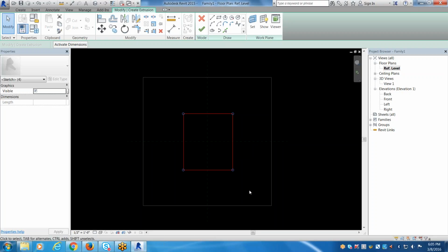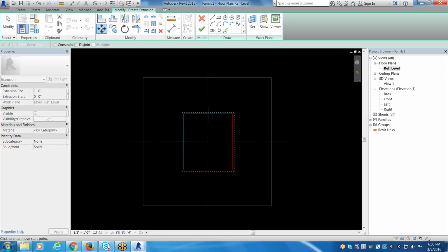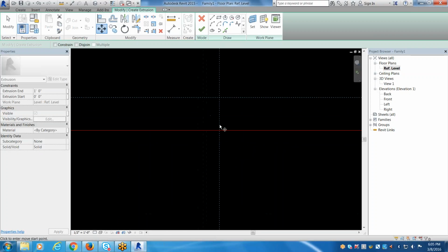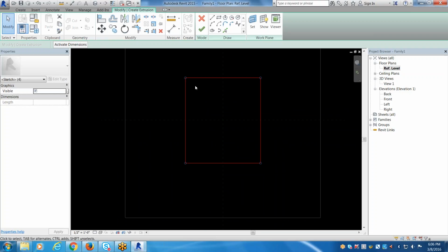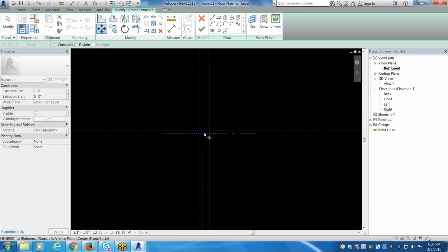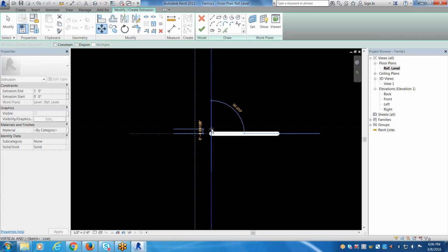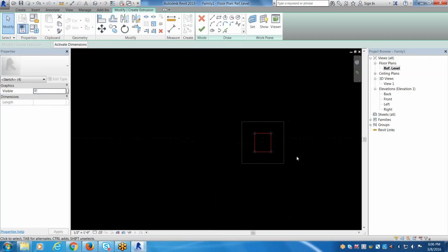Okay. The command for move is MV, no enter. And what you'll see is two midpoints. Like this is my horizontal midpoint, and this is my vertical midpoint. It tells you already. So I'm going to zoom into my top one here, find that midpoint, click it, and drag it over so that it intersects with that, right? And then I'll do the same for the vertical. I was pretty close, but never perfect. Okay?